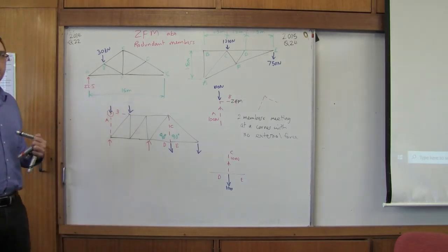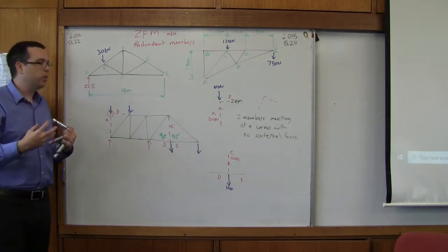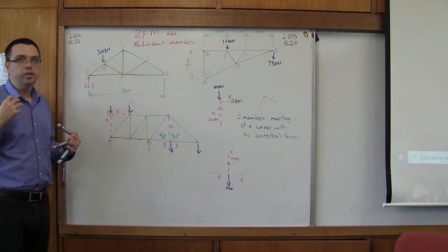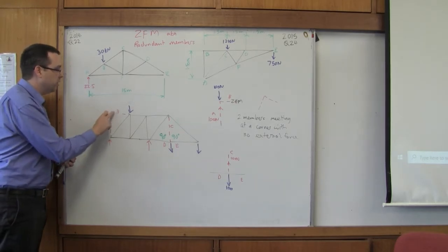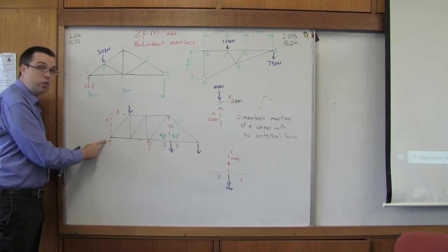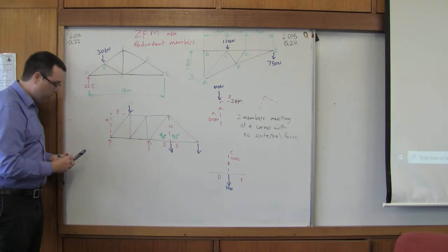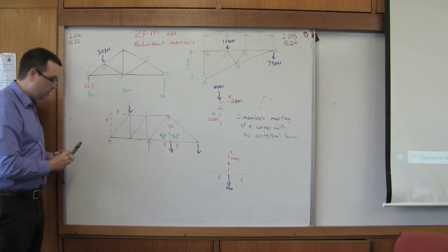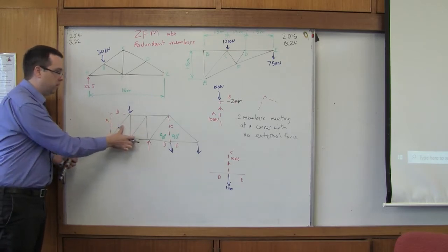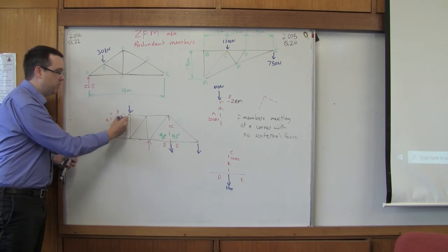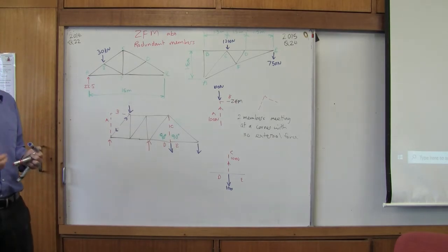So this is sort of drawing a little bit on method of joints, and I don't really like to talk about method of joints, but this is to help you understand how to recognize zero force members. So if we have a corner where two members meet and no external forces, even though this side has a force applied to it, this side here can't be the answer. What's going to happen is that the external force there is going to be matched by a force here and here. So it's going to have to be this member that provides the internal force in order to maintain the equilibrium.